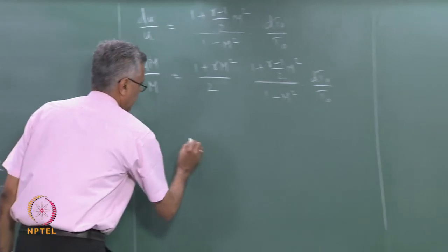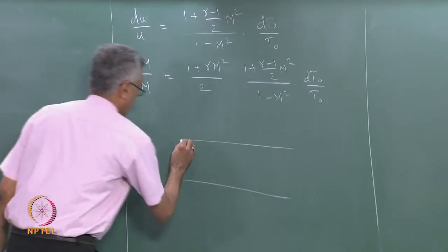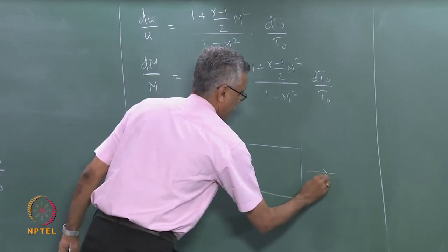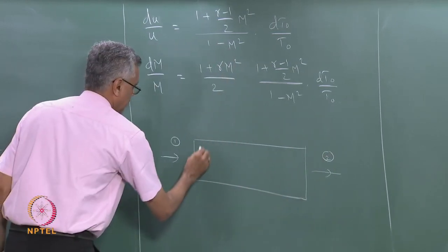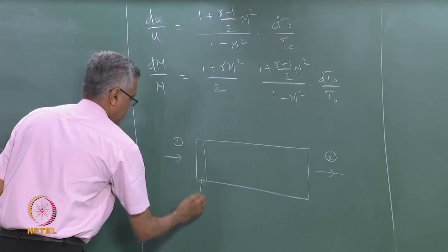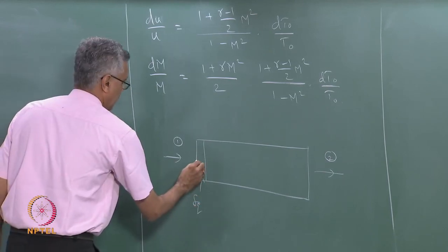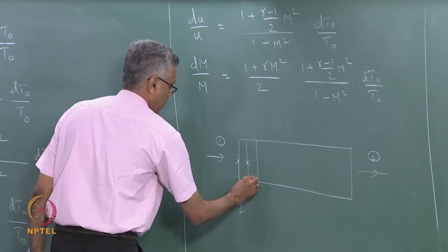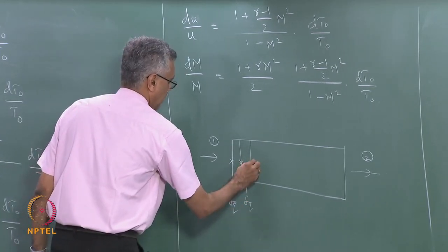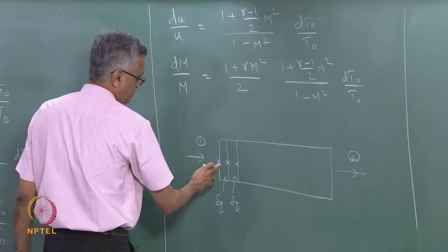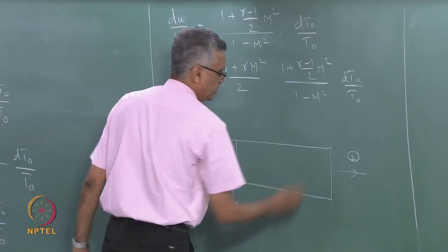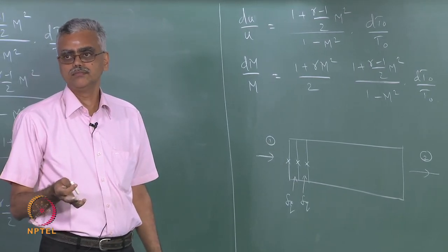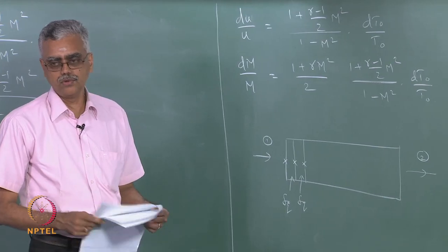So, basically as I said earlier, we start with state 1, right, and we look at say an addition of delta Q here, and so starting from state 1 we move to this state, then again we look at an addition of delta Q and we track this state. So, starting from here we track these intermediate states until we reach state 2 and we will plot this process on a TS diagram, right. That is what we will do in the next class.